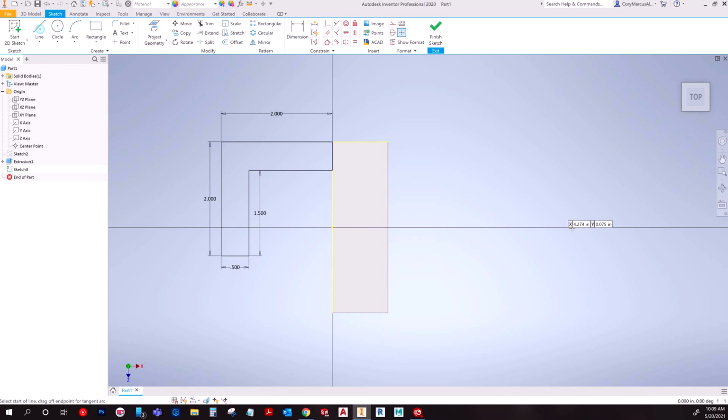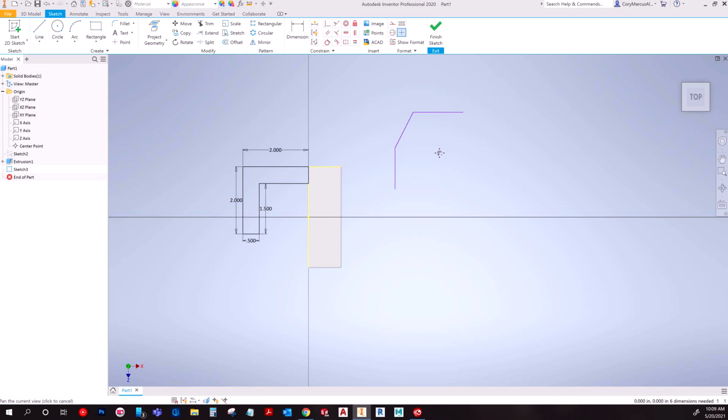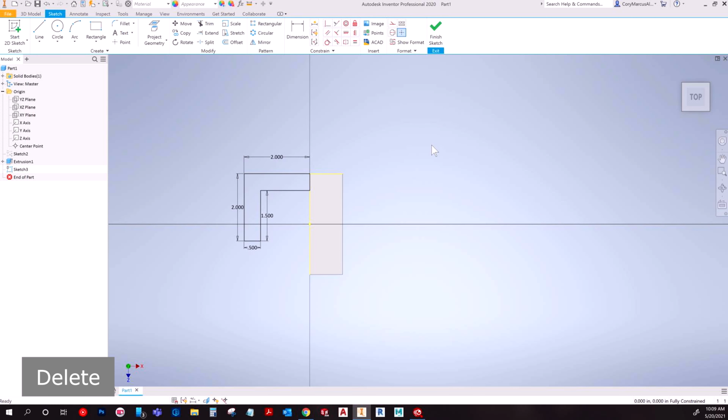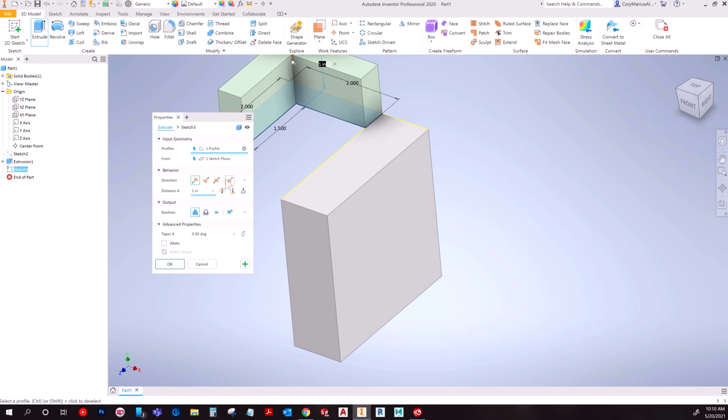So if I'm drawing, for instance, an angle here, if I were not careful about it, I may end up putting in like a 135, and then it'll basically lock itself in. It'll put a constraint in there because it thinks it knows what you want. And you have to be really cautious. So if you're doing angles in particular, it's good to exaggerate what it should look like. Say I know it should be a 45 even. I'll probably do it way up here just so I know it's for sure not implying any kind of constraint on its own. It's one of those things you'll get comfortable with in the program, but knowing what it's doing in the background is always a plus going forward.